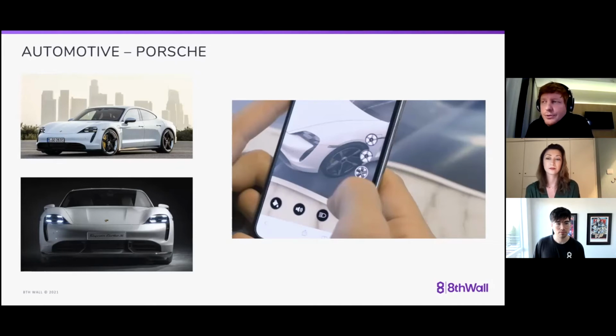So what you want to do is to reduce poly size. But of course you don't want to lose your details. So that's when you try to bake out some of the minor details to normal maps. You can also bake out ambient occlusion to give you this feeling of GI without having actual GI in the scene. So this is probably the first step, optimize your geometry.